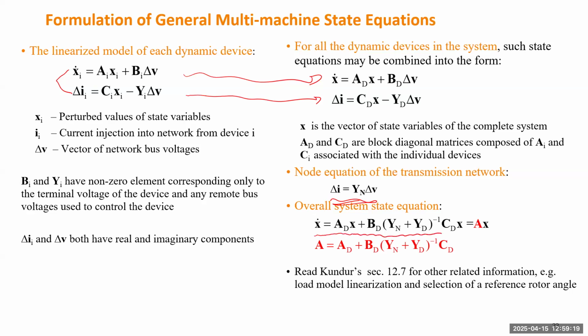So here, we solve the voltage from the linearized version of the power flow equation, and plug that into here to replace the voltage in the linearized model. And finally we can generate a purely ODE model. So that will be our standard form for the linearized model.